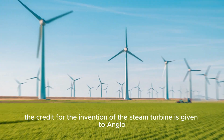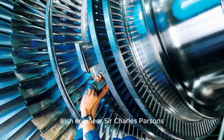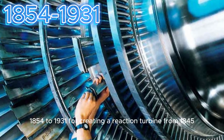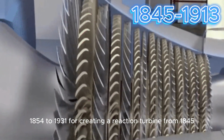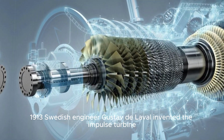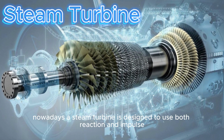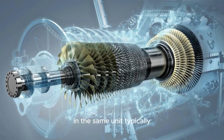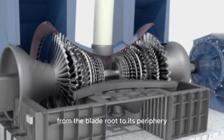The credit for the invention of the steam turbine is given to Anglo-Irish engineer Sir Charles Parsons, 1854 to 1931, for creating a reaction turbine. From 1845 to 1913, Swedish engineer Gustav de Laval invented the impulse turbine. Nowadays, a steam turbine is designed to use both reaction and impulse in the same unit, typically varying the degree of reaction and impulse from the blade root to its periphery.